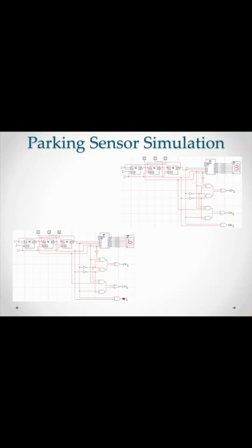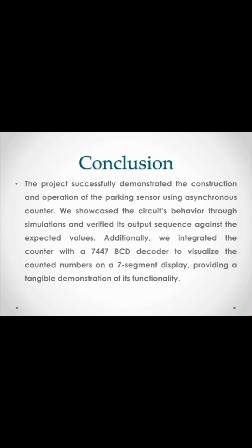The application is based on this logic. At the end of our project, the project successfully demonstrated the construction and operation of the parking sensor using an asynchronous counter. We showcased the asynchronous behavior through a simulation and verified its output sequence against the expected values. Additionally, we integrated the counter with a 7447 BCD decoder to visualize the counter number on a 7-segment display, providing a tangible demonstration of the functionality.